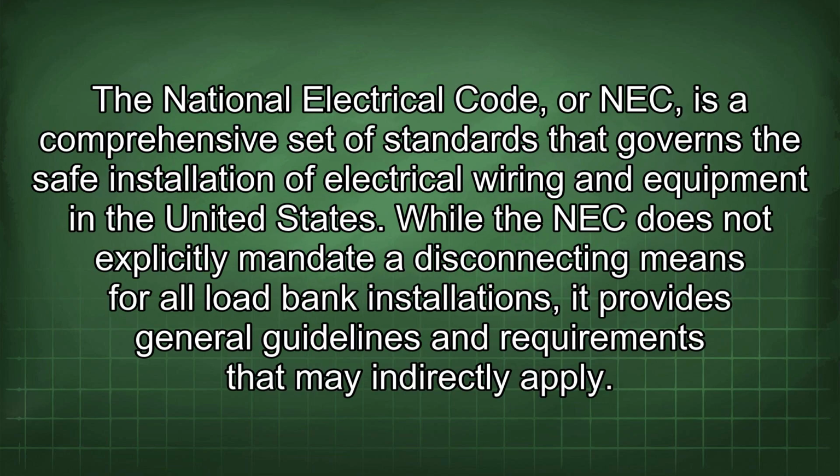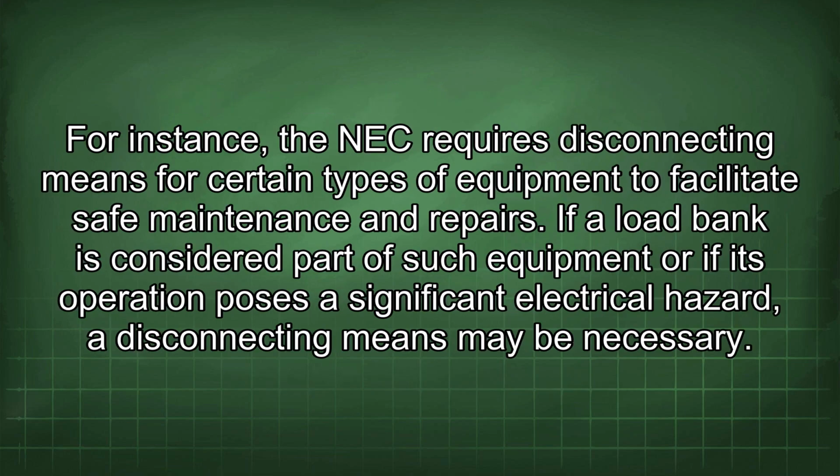The National Electrical Code, or NEC, is a comprehensive set of standards that governs the safe installation of electrical wiring and equipment in the United States. While the NEC does not explicitly mandate a disconnecting means for all load bank installations, it provides general guidelines and requirements that may indirectly apply. For instance, the NEC requires disconnecting means for certain types of equipment to facilitate safe maintenance and repairs. If a load bank is considered part of such equipment, or if its operation poses a significant electrical hazard, a disconnecting means may be necessary.